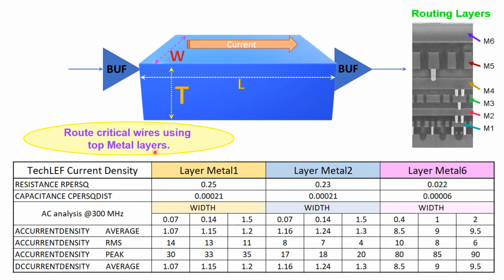That is why, in routing, a higher thickness metal layer is better used for critical wire routing. Even in clock routing or special signals which need to be routed with lesser delay, we can use the thick metals. Or even for power routing, for reducing the IR drop, the higher top metal layers can be used.